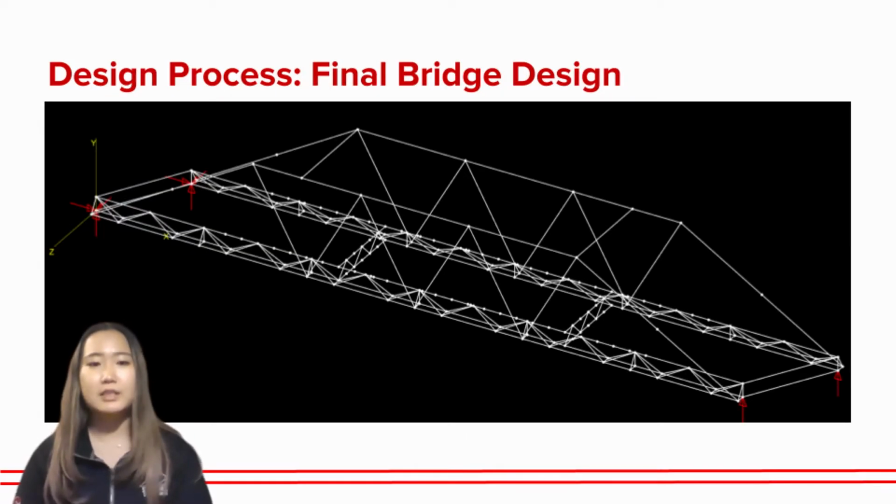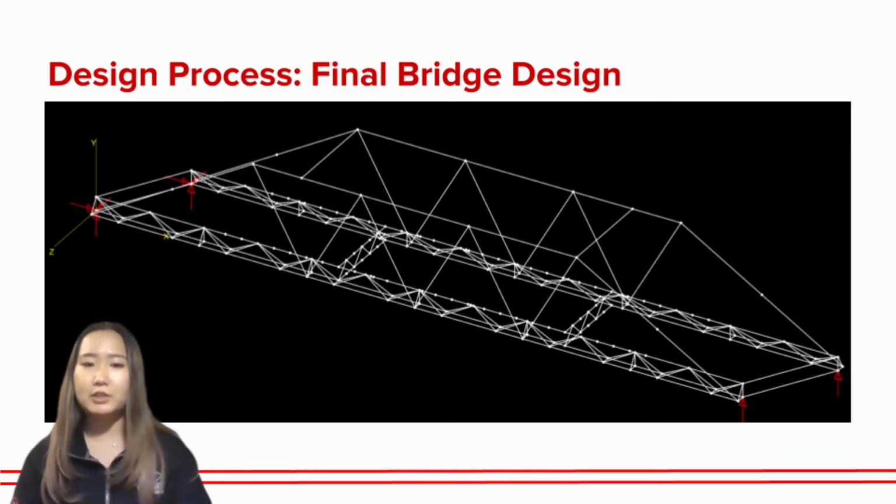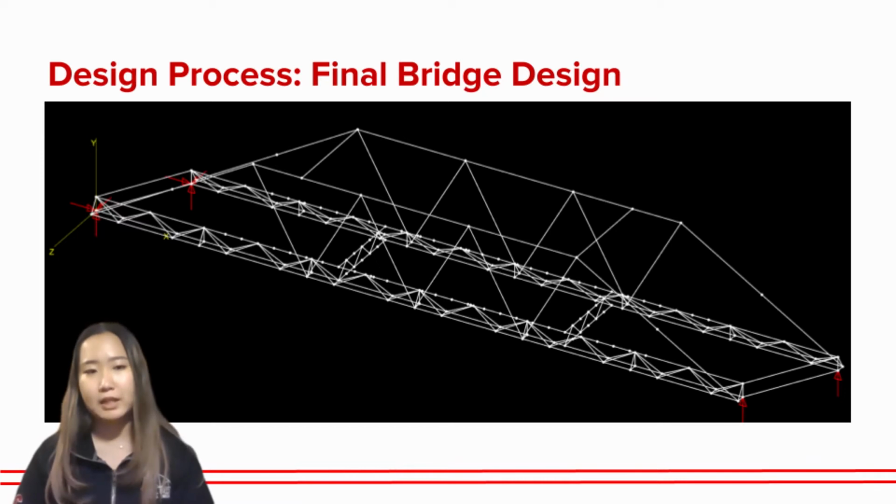This current design received the most votes because it had the potential to produce amazingly low deflections due to the space frame and large upper truss height. Each side of the bridge can be broken down into roughly 6 members, which makes constructing over the river significantly easier than with a 7-member breakdown.